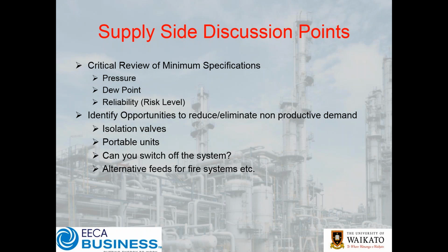What was interesting though was the site was only used 50% of the time, sort of 2 shifts a day, 5 days a week. Outside those shifts they had a lot of maintenance work that was done, and of course depending on where they were in the factory or plant, they needed access to compressed air to do some of their maintenance tasks. So as a result, the compressed air system was largely kept on so that they had access to compressed air for their maintenance strategies. When we sat down and identified this and talked them through it, we said, look, you might not be able to fix all these leaks, but you can eliminate half of them just by turning the air off when the plant's not being used.